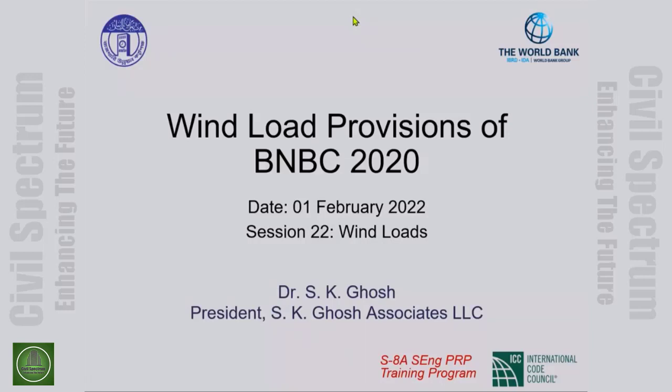Today's topic, as Bodhi just said, is the wind design provisions of BNBC 2020, which are based on ASCE 7-05, the 2005 edition of the US standard titled Minimum Design Loads for Buildings and Other Structures.